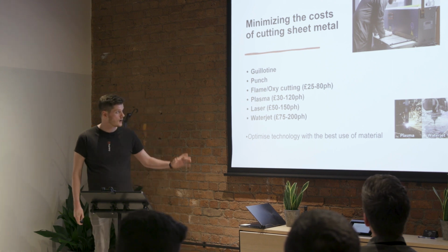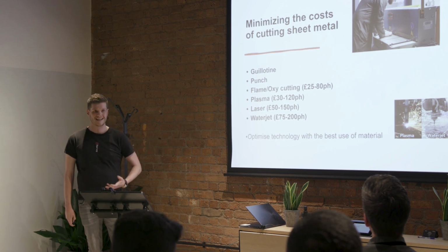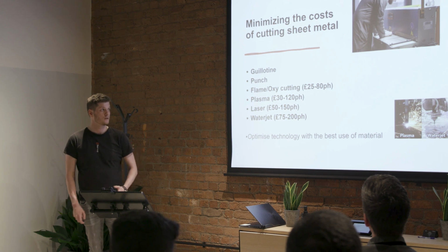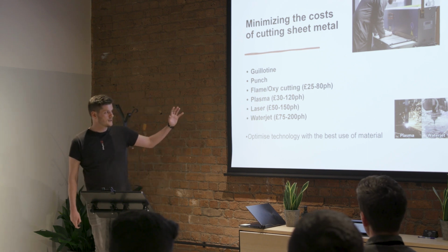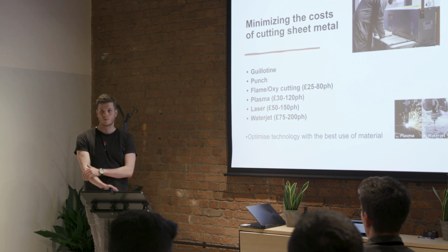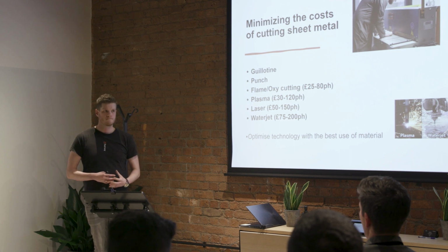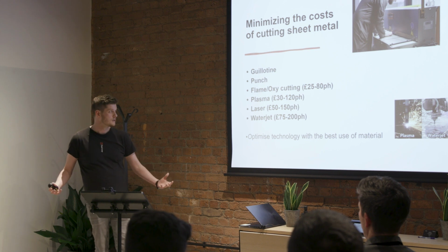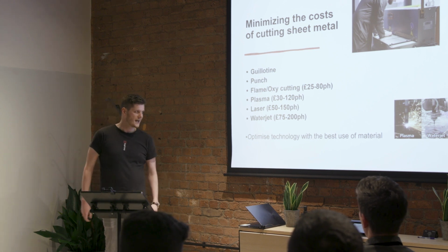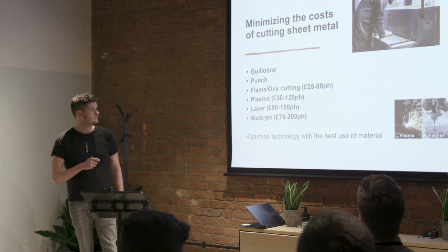So figuring out which one of these you want to go with and what you want to have on your project can have a large effect on the overall cost of the job itself. Now, I do see quite a few people coming in and asking for water jets again when they can probably accept plasma just because they've heard water jet is the best. You don't necessarily need to buy a Lamborghini when a Ford Focus will do. So really considering what the application of your parts is always going to be important here.